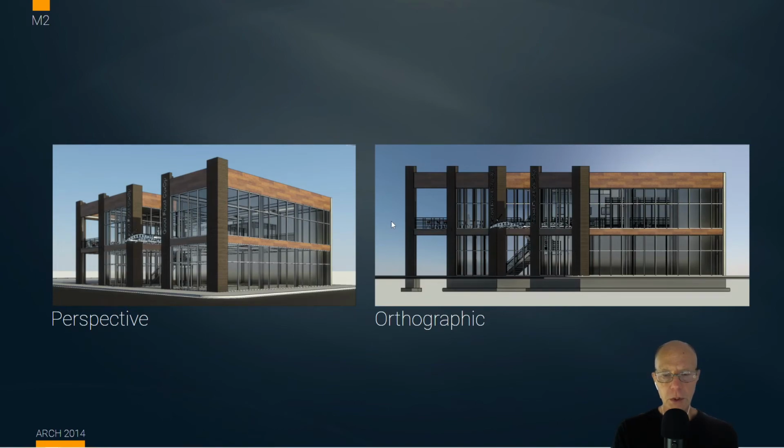This is an illustration of why perspective is really important to us, the idea that we can create perspective. This is a view of the building that we will be creating, and we're looking at it from the same vantage point. And I've changed two settings in the software. One, I've said look at it from the camera view and the perspective, and now you'll notice how components of the building that are equal height become shorter as they get further away from the viewpoint. So these are both moving in a two-point perspective here.